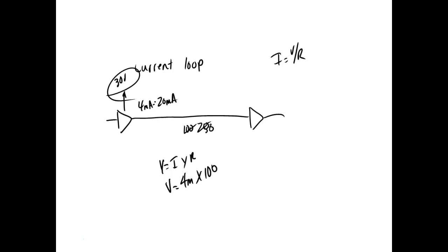It's just like your ohm meter. Your ohm meter is a constant current source. People don't understand that. When you put your ohm meter across a device, it outputs a constant current, like 1 milliamp. You can measure that. Then it raises its voltage until 1 milliamp flows, and then it measures the voltage. But it doesn't say this is the voltage; it puts it up as ohms, right? So your meter is a constant current source.